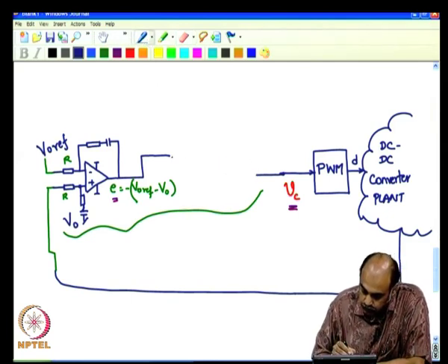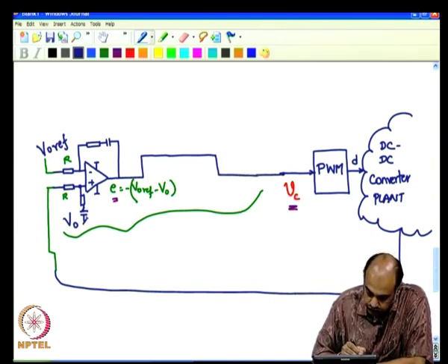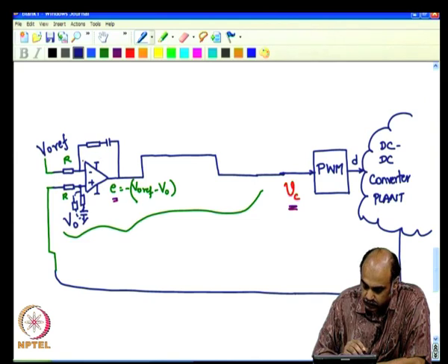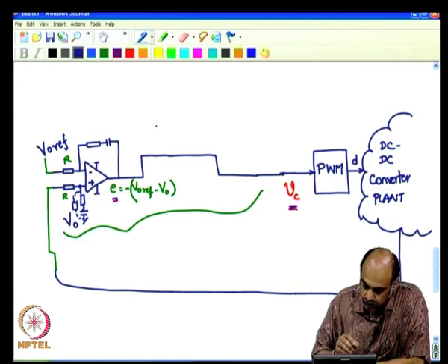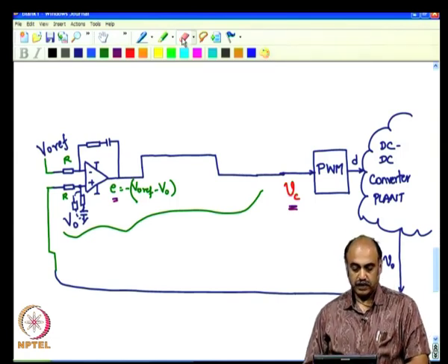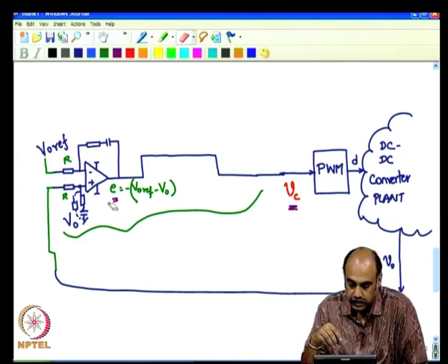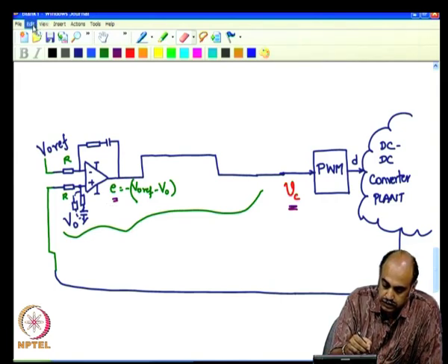First of all, you need to have a resistance across to provide a bias current path, okay, which will introduce a low pass filter and change the equations a bit. So, it is better to not do an oversimplification and have everything on with just a single op amp. It is easy also for you to debug to keep the earlier 2 op amp structure.